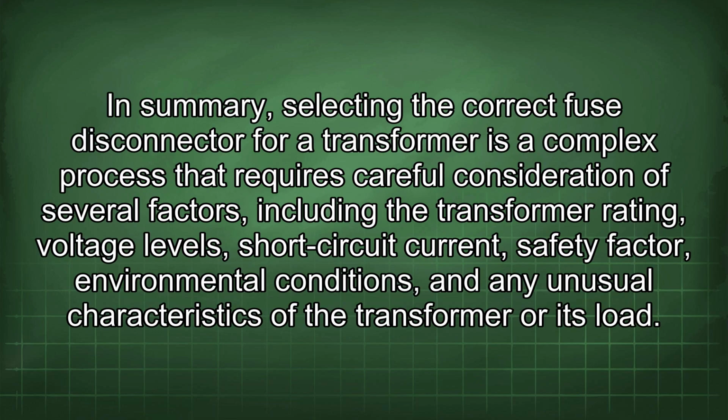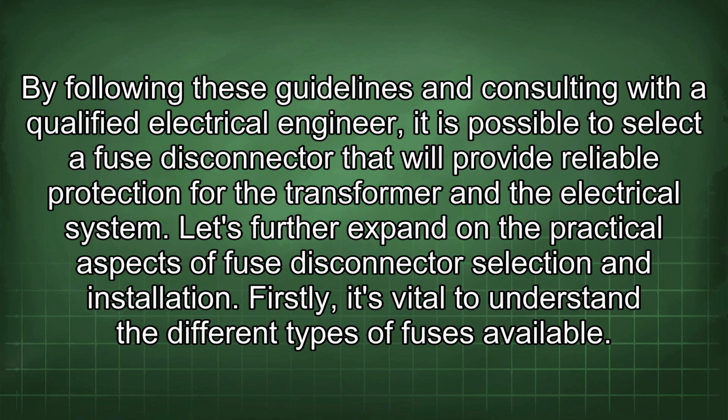In summary, selecting the correct fuse disconnector for a transformer is a complex process that requires careful consideration of several factors, including the transformer rating, voltage levels, short-circuit current, safety factor, environmental conditions, and any unusual characteristics of the transformer or its load. By following these guidelines and consulting with a qualified electrical engineer, it is possible to select a fuse disconnector that will provide reliable protection for the transformer and the electrical system.